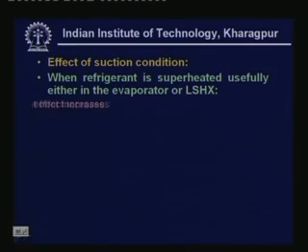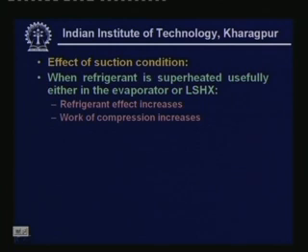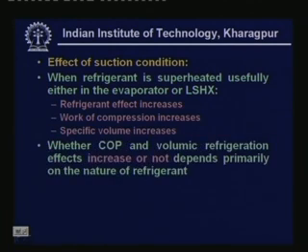Okay. So when refrigerant is superheated, usefully either in the evaporator or liquid suction heat exchanger, refrigeration effect increases, as I have already discussed, work of compression increases, specific volume also increases. So whether COP and volumetric refrigeration effect increase or not depends primarily on the nature of the refrigerant. Okay.